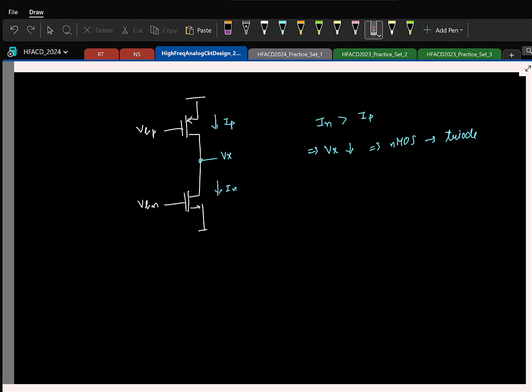So this is not a great way to have the circuit, because as I mentioned sometime before, this is like having two current sources in series and then trying to find what this voltage is, right? So ideally, if one current is greater than the other, this voltage will either increase or decrease, and even if they are exactly same, it is not clearly known what is this output, right?